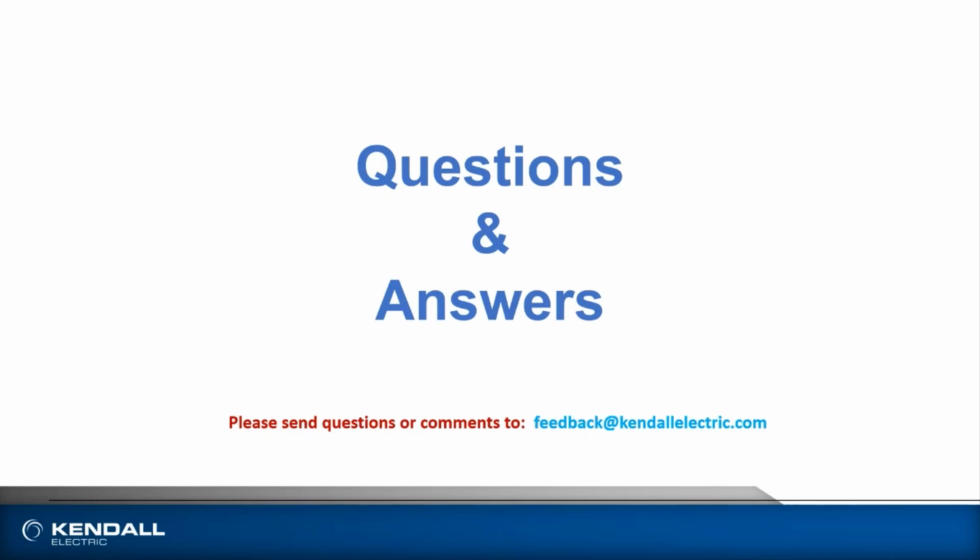I've actually had this conversation with a local customer, and it depends upon what you have as an installed base. Eventually, even if we get to 2030, the MicroLogix 1400 will go away. So do you want to migrate at this point in time, or do you want to migrate a little bit further down the road? The immediate is I can move from a 1200 to a 1400 without a problem, still keep my existing programming software and the platform I'm familiar with, but you will eventually want to get yourself to the point where you're looking at migrating towards what's going to be available in the future to keep your facility up and running.